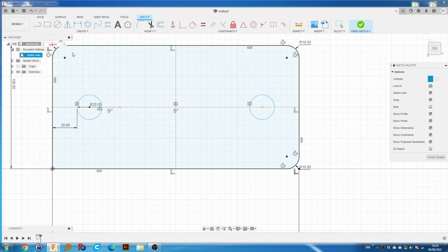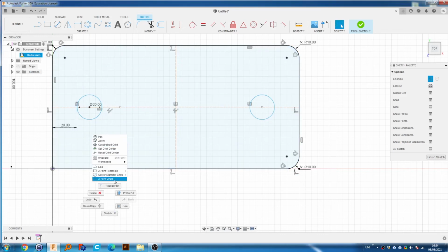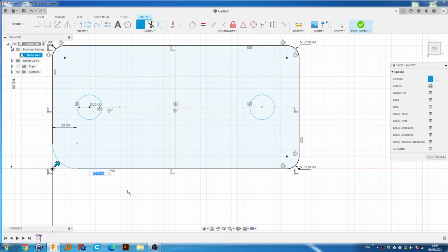And we can't use rad because it's probably a preserved keyword. So let's put my rad or something equals 10. Now here we can type in my rad. And we're going to repeat the fillet and my rad.